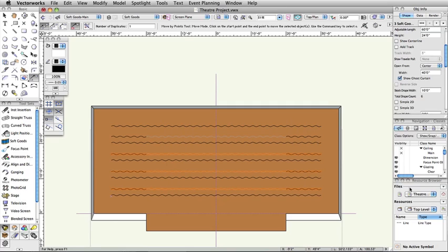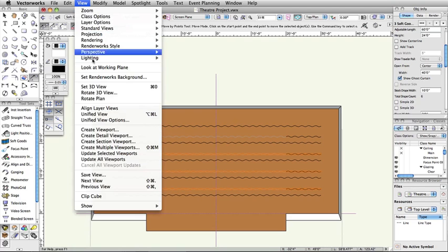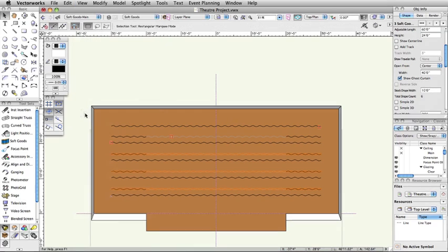Note: when creating hybrid 2D 3D objects in Vectorworks, it is a good idea to occasionally switch to a 3D view to check your work. It's possible to enter an incorrect height or Z elevation and not notice it while working only in a top plan view. When working with multiple layers, before switching to a 3D view, you should make sure Unified View is activated. This command will align the layers with the active layer so they appear correct in 3D views.